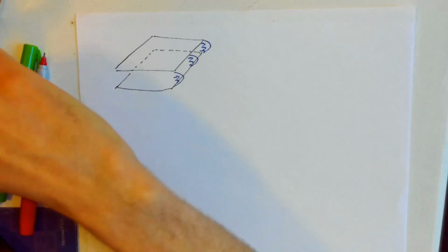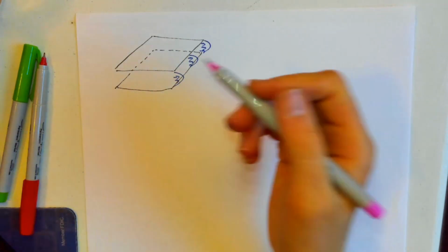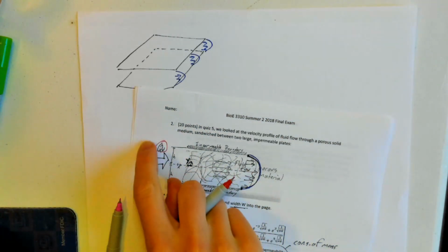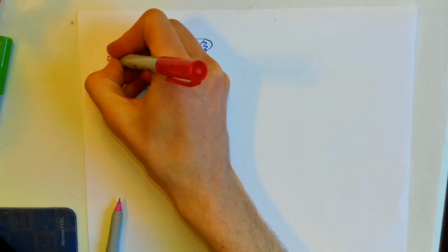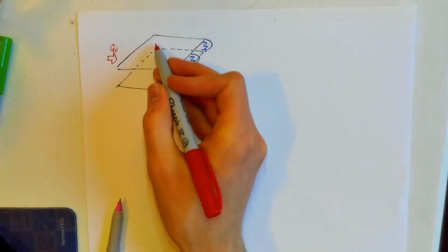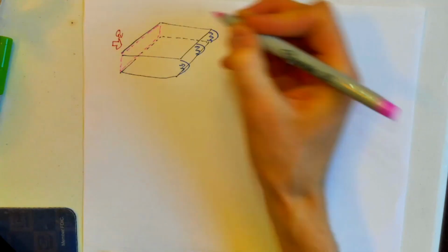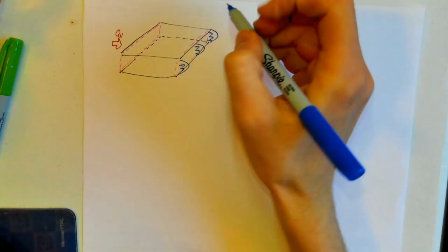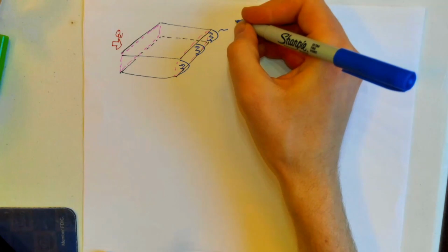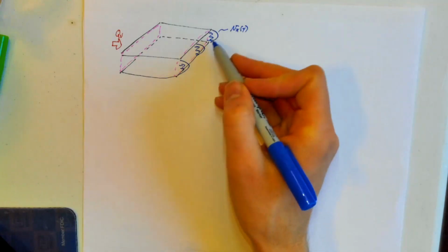I might want to define a control volume that allows me to relate a volumetric flow rate in, which I'll treat as an unknown, to this velocity profile out, right? So we have some as of yet unknown volumetric flow rate that essentially flows into this face right here. Then I have this outlet face right here, and this is my Vx as a function of y. And we're assuming that this isn't really varying with z.